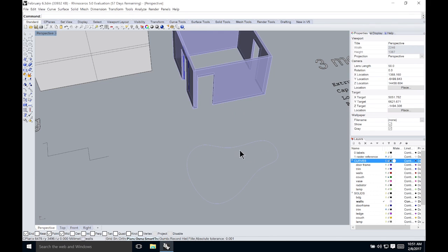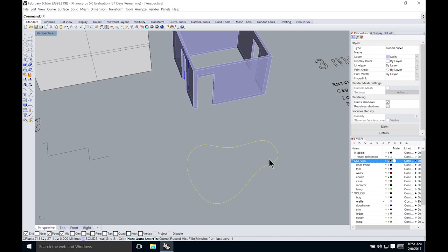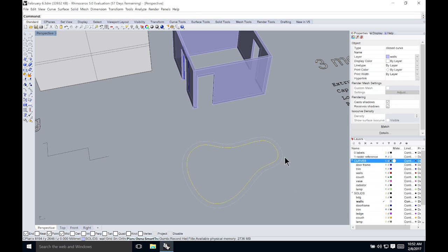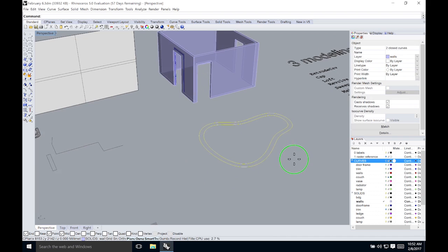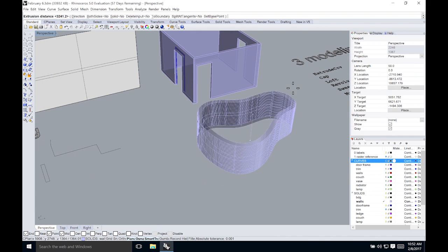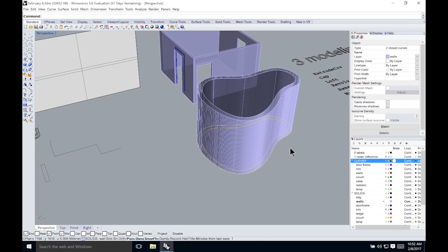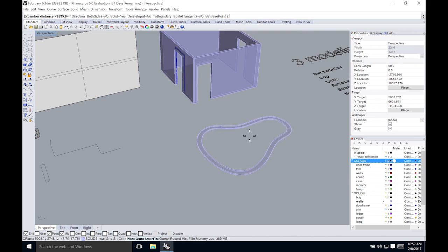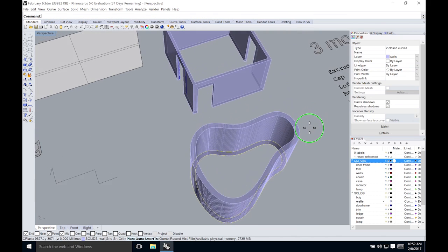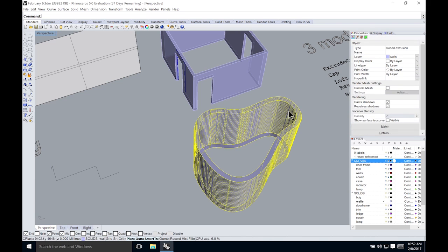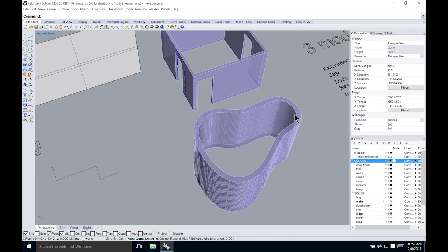But if I wanted to go back to my curve, I can actually offset this curve, and once again I'll type 200 and then extrude these curves together. And the nice thing about this is that, as long as you have the solid option checked yes, then it's going to create a solid from these two curves. So that's a really handy thing.